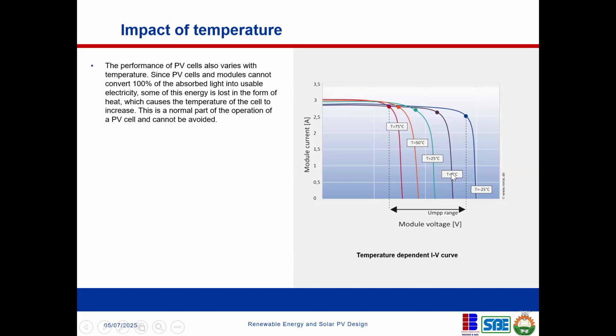But the point is that once the temperature begins to increase, the voltage begins to drop, and it drops significantly, right? Compare with the current. You can see the current really moved, okay? From 0 degrees centigrade to when the sun was at 75 degrees centigrade, the current did not move as much, but you can see how much the voltage has moved, right?